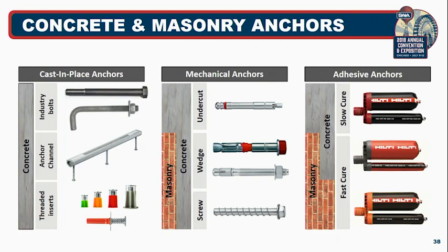Then when it comes to adhesive systems, two main types of adhesive systems are the slow cure and fast cure adhesives. Okay? When you're looking at utilizing an adhesive anchor system, there are certain things that need to be taken into consideration. One is the cure time of the product. Some products cure up in like 30 minutes, others take a day, others take maybe even 4 days at room temperature to achieve full cure. So cure time is an important thing to look at with adhesive systems.